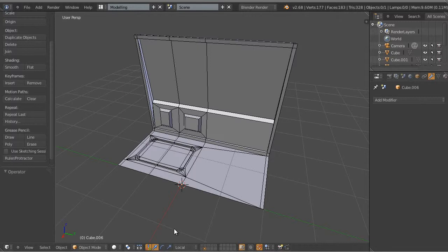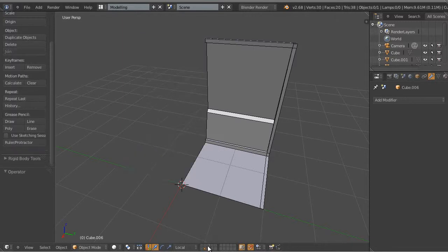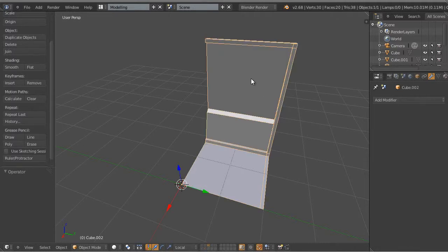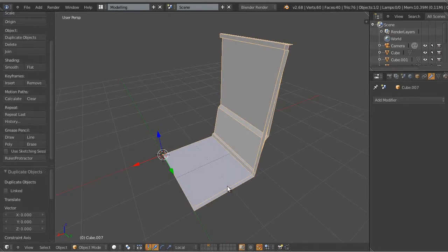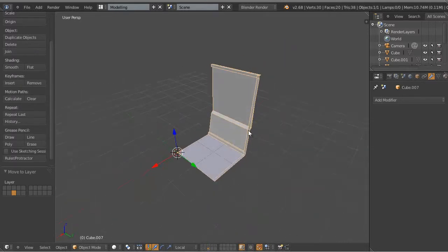So to do that I'm going to be relying on our trusty friend, the famous quarter section. So let's go back to this layer here and select that quarter section and duplicate it by pressing Ctrl D. Press Enter on the keyboard to confirm that duplication, and I'm going to press M to move it to this central layer here at the bottom and just switch over to that layer. So here we have our quarter section that we're going to be using for creating a corner section.